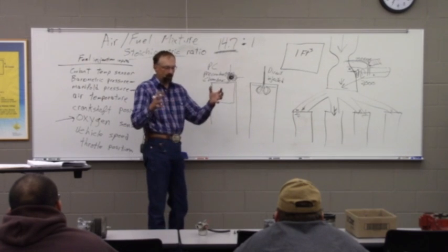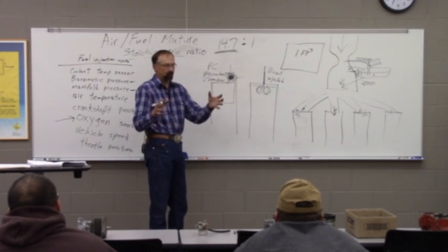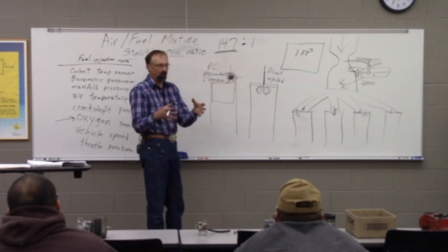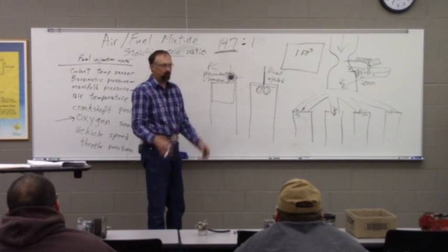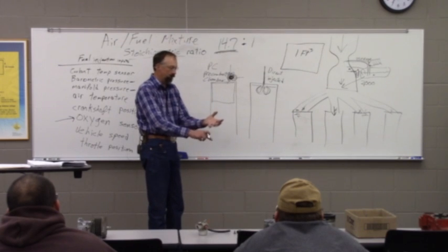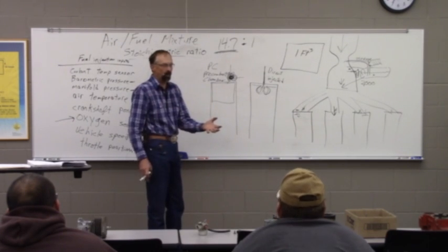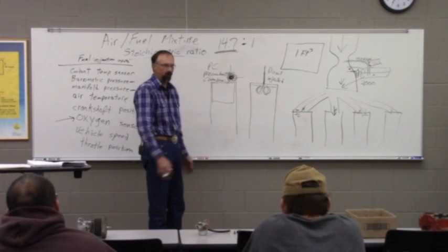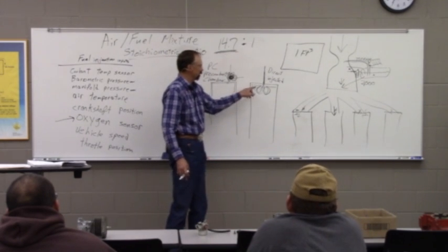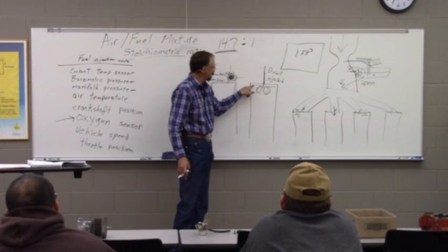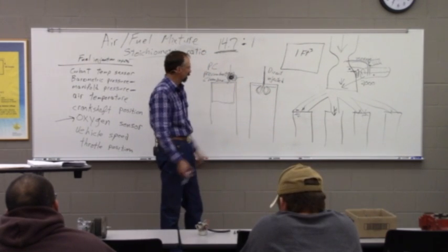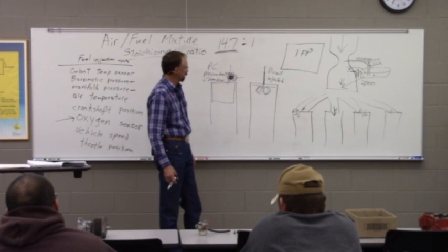So the more surface area there is of metal touching our combustion, the more of what we call quench we have, and the less perfect reaction we have, where we're going straight to the power we want to create and the carbon dioxide and water, with less of the trash we would rather not have. A lot of the trash and undesirable side effects happen at what's known as the quench area, all the surface of metal that's touching our combustion.